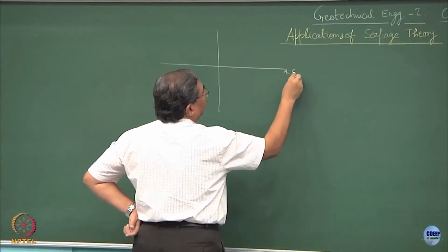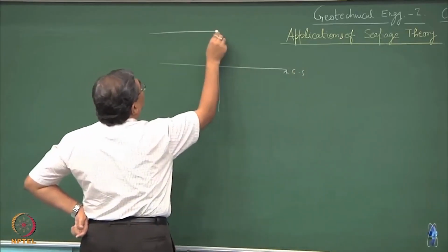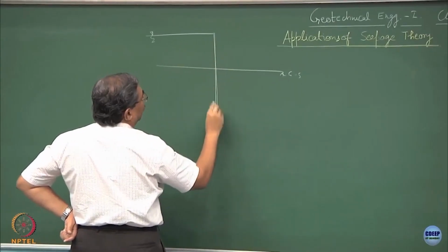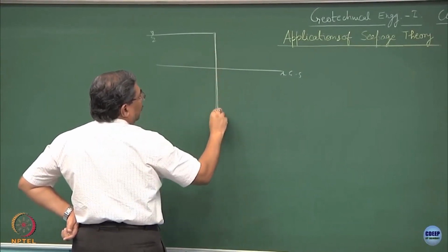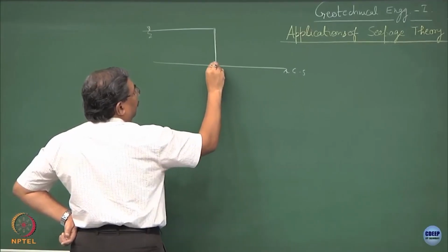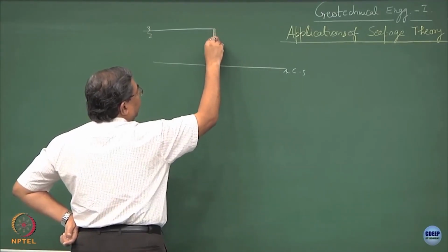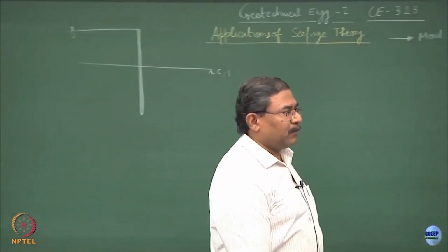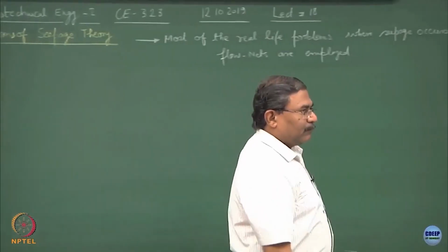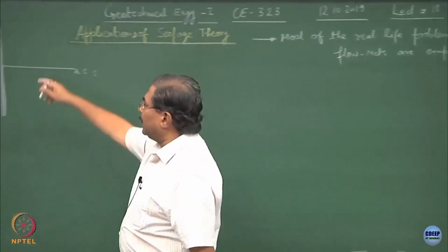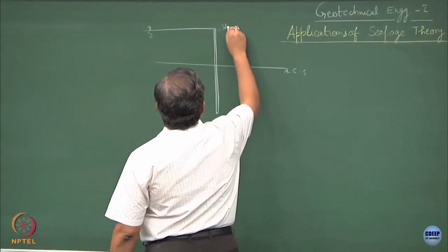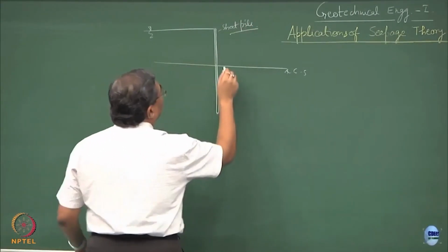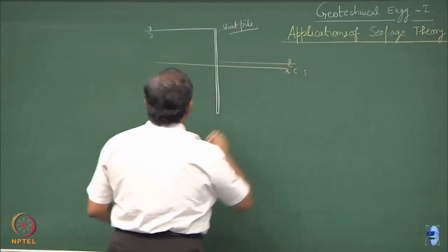So, this is the ground surface, and by retaining this water, this is the sheet pile of certain thickness, certain modulus of, what do we call it, E into I, stiffness modulus. In a structure analysis you must be doing the course, E into I is the stiffness modulus. So, I can select an element, this becomes sheet pile, and this is how the seepage regimes develop.